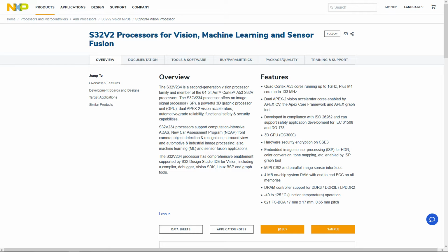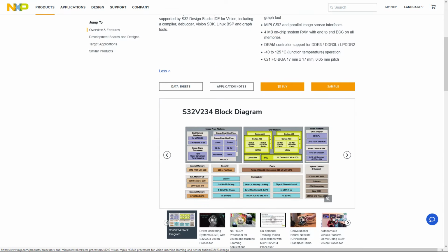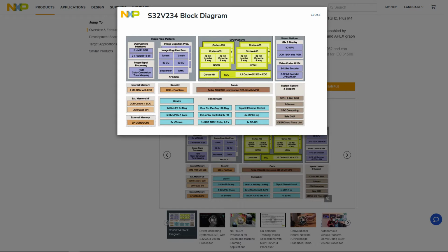And the reason why we selected the S32V234 is primarily that when you're designing this board, there were certain things that caught my attention. One of them is, you could design the board on an 8-layer PCB and you don't need to have 12-layer stacks, which is important because when it comes to fabrication, the more layers, the more expensive it can get. If you can minimize the layers, you can drastically save on cost, and the design of the system is also much easier.